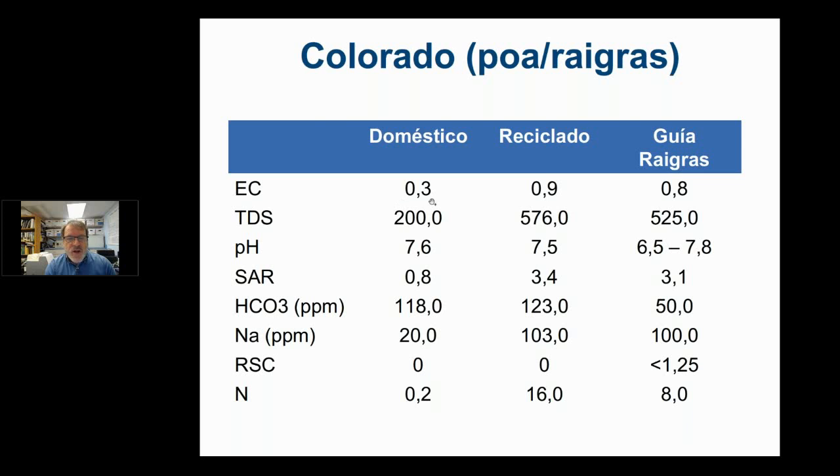As you can see, the electrical conductivity is low, and we would normally call that possibly a problem water because the electrical conductivity is so low. The SAR is low also, and has very little sodium. About 10 years ago, they had to switch to recycled water. And so this is on the course. So we're going from this water, 100 years of this type of irrigation water, to now recycle water forever, just because of drought conditions, that they're trying to find alternative sources to domestic water.